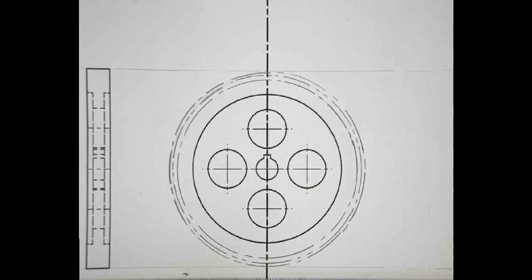As far as completing the sectional side view, we will start by drawing the outline of the gear, so it would just be a rectangle similar to what's shown in the side view with hidden detail. We have been told that the thickness of the gear as well as the pinion is 20 millimeters, but we are drawing to a half scale, so we'll have a thickness of 10 millimeters.